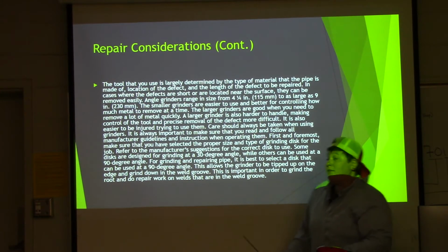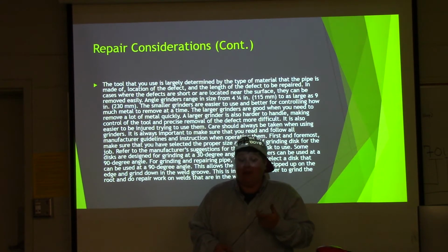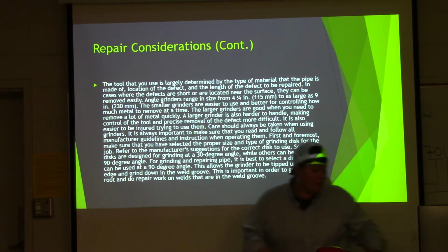With that being said, whenever you're using a grinder in the shop, make sure you have on all your correct PPE: safety glasses, gloves. Make sure that you have the guard on your grinder. Don't grind or use a cutoff wheel without your guard on there.